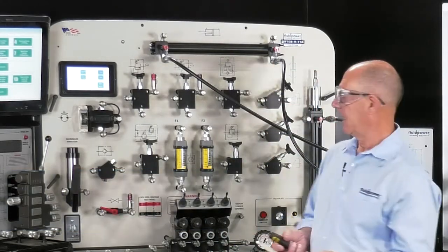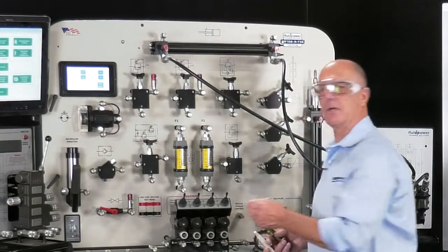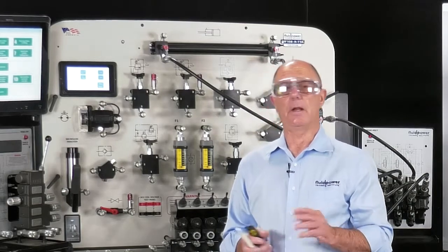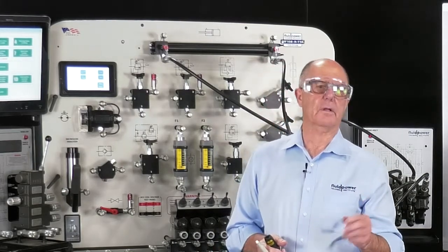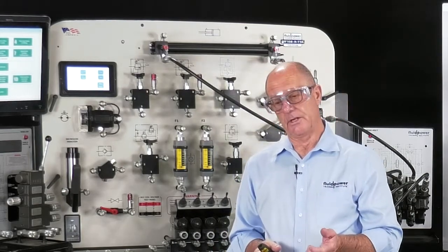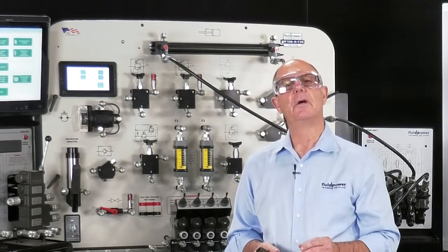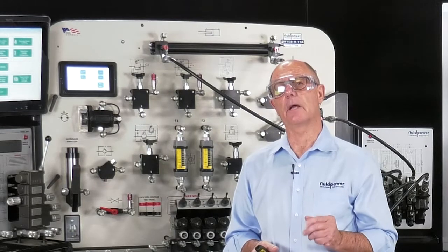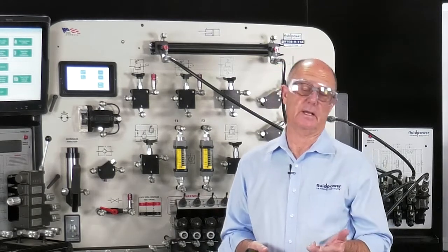Meaning this. Let's say I test a directional control valve, which is a leaker by design, and let's say it is brand new. And let's say the amount of oil coming out of the Porta-Power is so minute that it can't make up the leakage through a brand new valve. That'll tell me the valve is bad when the valve is actually good.